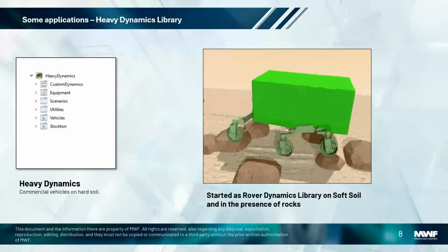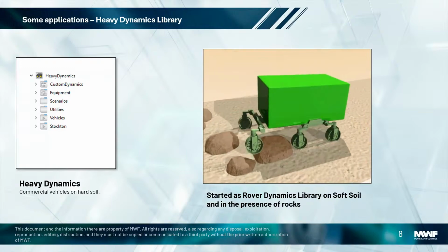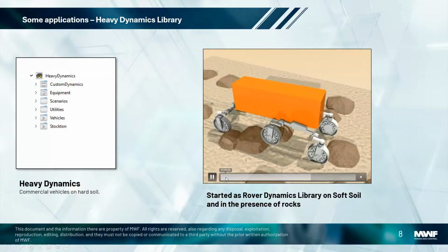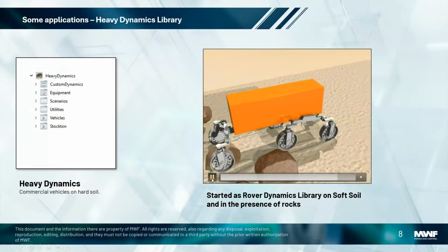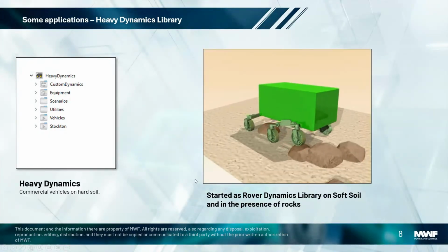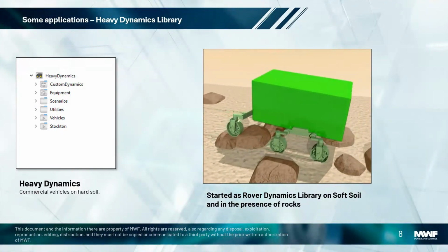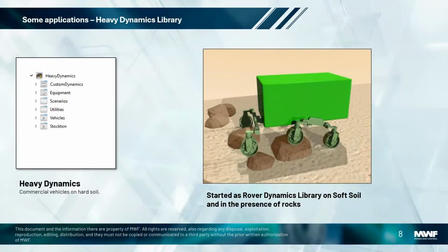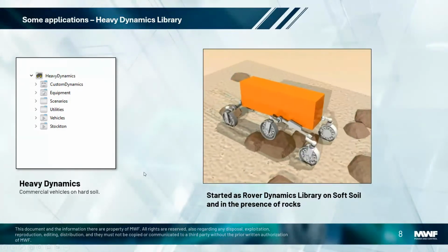And as you can see, it is able to reproduce the trafficability of a planetary exploration rover with many wheels in contact with soft soil, in contact with stones, many stones at the same time, producing tracks on sand, different types of sand, etc. Both sinkage and slippage, both lateral and longitudinal, are able to be modeled and simulated in this library.